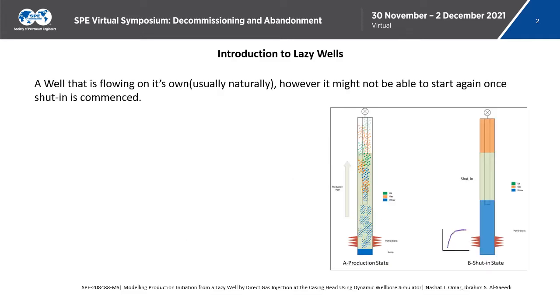Whenever a well is shut in, a phase segregation is expected. And whenever the different phases segregate, different fluids will accumulate in different sections of the well. This will increase the bottom hole pressure and increase the wellhead pressure as well.